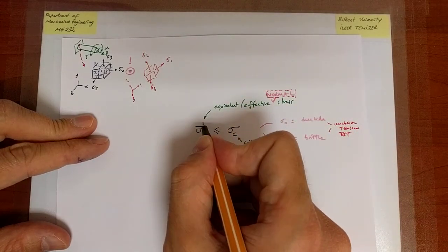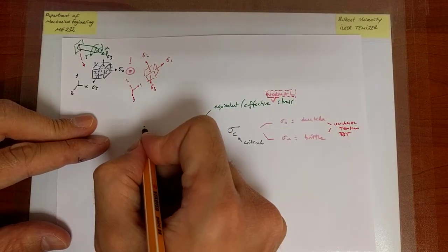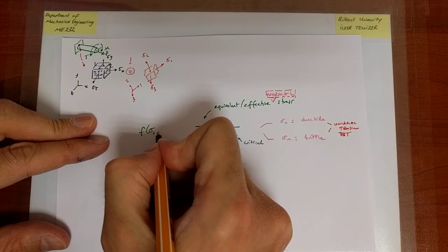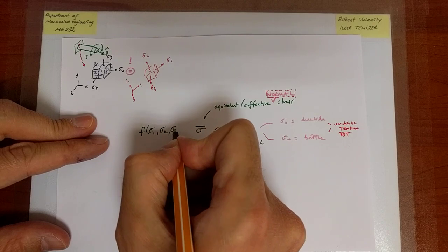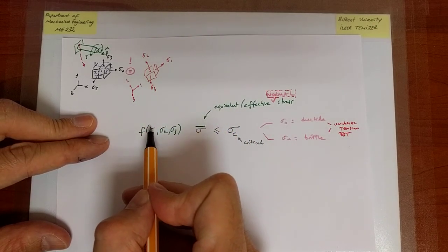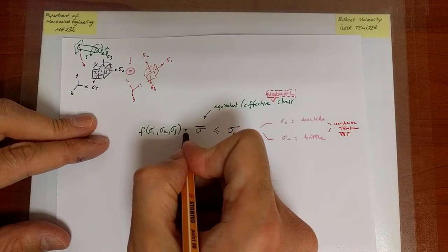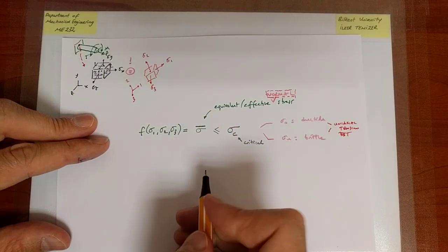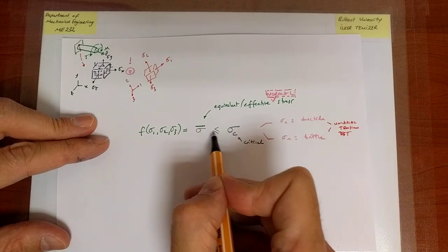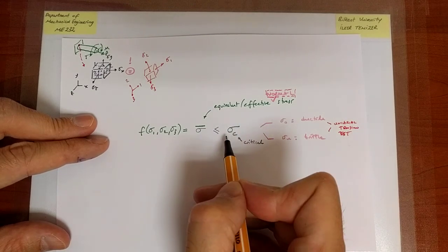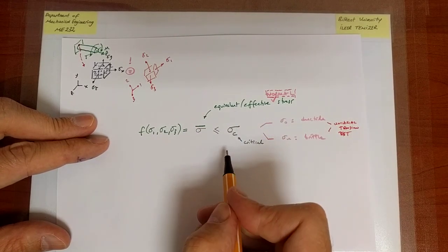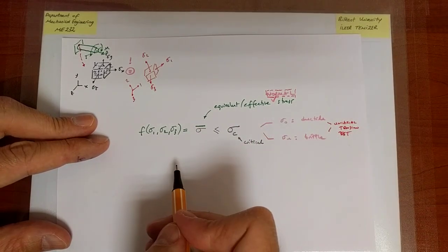So you calculate the equivalent or effective normal stress. How do you do that? Well, you construct a function that takes in all the values of the stresses that you apply presently in terms of the principal picture and spits out a single normal stress. And then you can think of this stress now as if it were coming from a uniaxial tension test, and therefore you compare it against the critical value that comes from such a test.